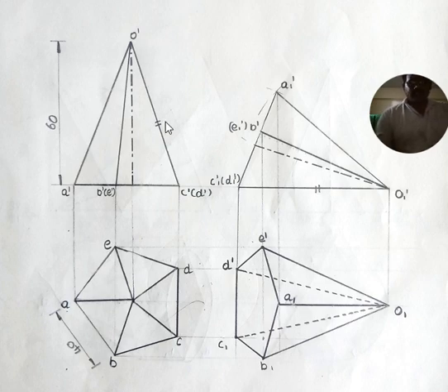So here, two slanting edges are coinciding. When I see from here, OC and OD, these two slanting edges are coinciding and we get only one line instead of two. But in the front view, I am able to see only one slanting edge, that is OC. So that is written here. The D dash is written inside the bracket because the OD slanting edge is coinciding with the OC slanting edge. In specific, the OD slanting edge is invisible during the front view.